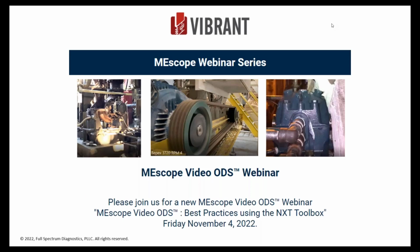Okay. So my high-speed camera is my phone, and high speed is relative, but at 240 frames per second, you get an Fmax of 120 hertz, and for most applications that we're looking for phase, that's plenty, and we should be able to use it and enhance what we normally take as data. So now we have a visual vantage point that is really good.